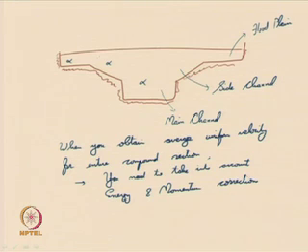You know that momentum fluxes, mass fluxes, all these occur between the sub areas. So those corrections you require. When you try to compute, for example, the mass flux between these two sections, and if you incorporate some portion of the main velocity along this section, you need to incorporate the corresponding correction coefficient. You cannot take the entire velocity.